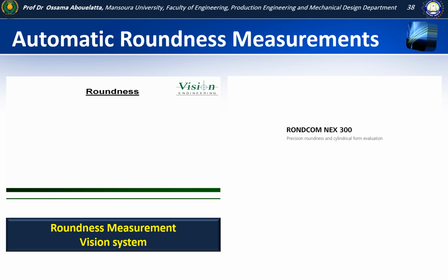Roundness is sometimes referred to as circularity. What we shall first do is take an out of round part, and then we'll find the centre of rotation, or the axes of rotation. This is sometimes quite difficult to find, since we have to find the least squares best fit circle. Then from that least square best fit circle, calculate out the centre of rotation. We then rotate about this centre of rotation, and with a dial indicator we'll measure the roundness.